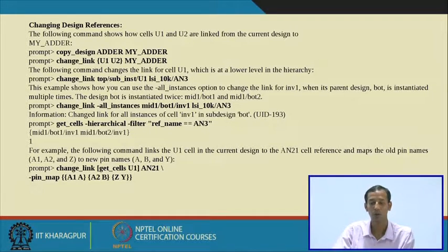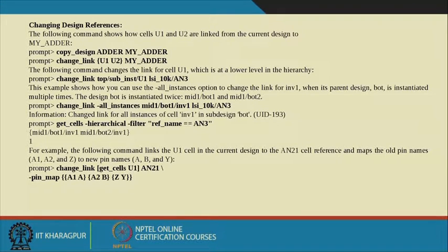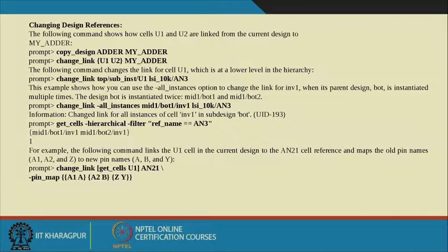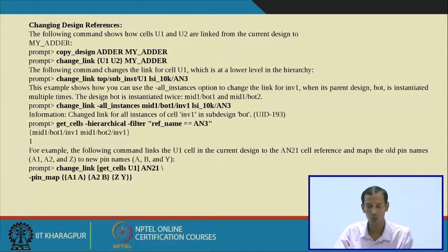That means you make a copy of that particular adder, here named myadder, to another adder. So copy_design adder to myadder. Then change_link U1 and U2 to myadder.